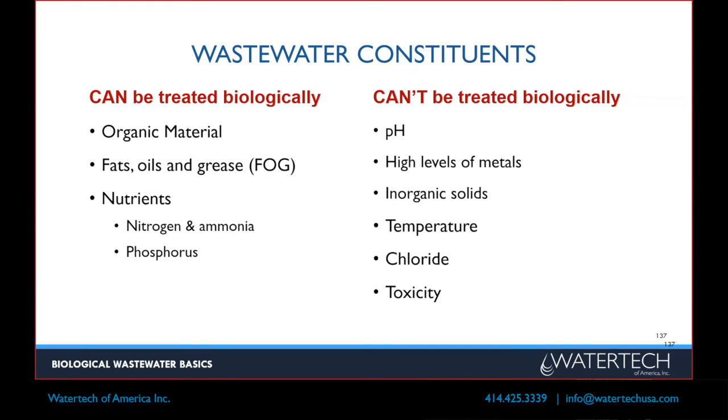And then we'll talk a little bit about toxicity as well. There are chemistries used in industrial processes, especially food plants. You need to kill things in your piping and manufacturing facility so that you don't have any toxins or bacteria in your food product. Well, those things carry through into a biological system. If they're still present, they're going to affect your biological system. If they make it into the effluent of your facility, you'll have toxicity issues in your receiving water.